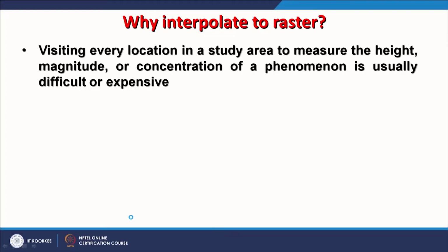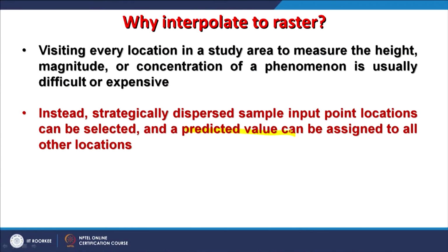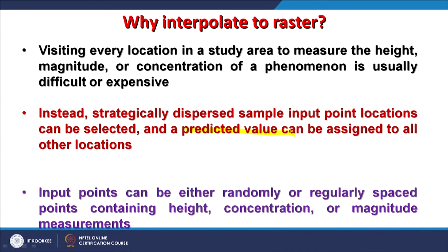As you know, visiting every location on the surface of the earth and collecting the height information is impossible, because there are terrains which are very difficult for humans, and it is not possible to generate a surface for the entire globe. So some techniques have to be employed. One technique is, wherever it is possible, collect the heights, employ the interpolation techniques and generate a surface, or predict values for each cell. That is what we are doing in interpolation.